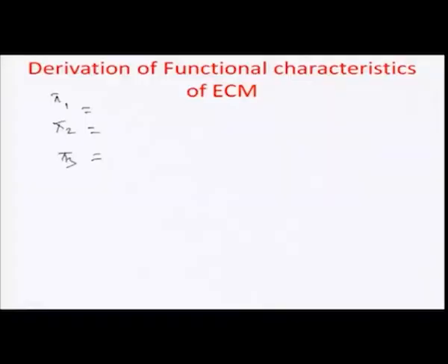So, the parameters we have earlier illustrated are the depth of melting, the beam power, the velocity of rastering of the beam, the thermal conductivity, the volume specific heat of the material, the temperature of melting, and finally, the beam diameter.